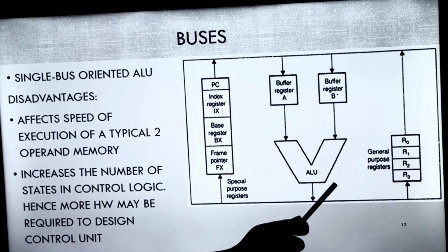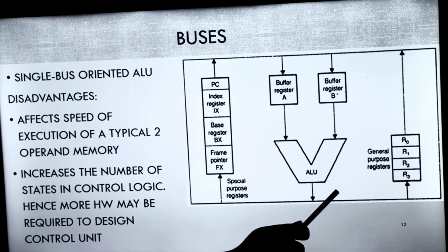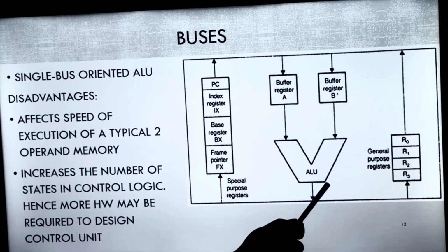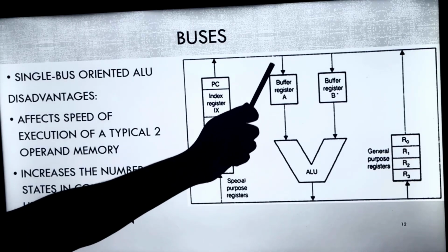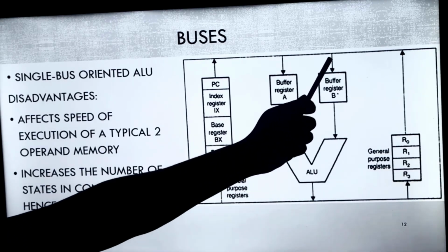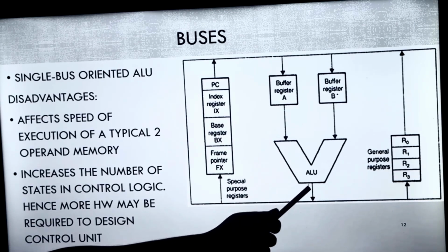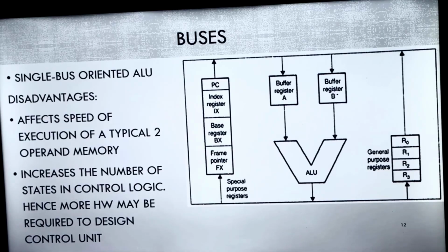The time will be very less. It will be milli nanosecond. You cannot say that it will be one clock cycle for performing only this A plus B. So in one clock cycle we'll get A, second clock cycle I am getting B. In third clock cycle I will perform this operation and send this output to the output buses. So I need total 3 clock cycles to perform C equals to A plus B for this.